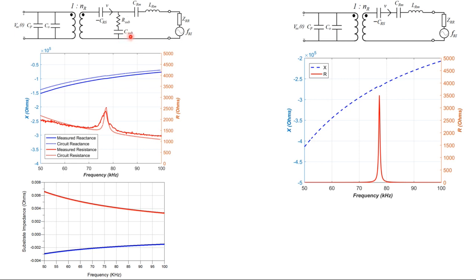So C sub can be, again, the compliance of the backing, which is much less than the front plate compliance, because the front plate is easily depressed. It's silicon in most cases, which is easily depressed by the ambient medium loading and the electric field that exists between the CMUT electrodes. So CRM is much more compliant. You can say CRM is going to have a larger value than C sub, right?